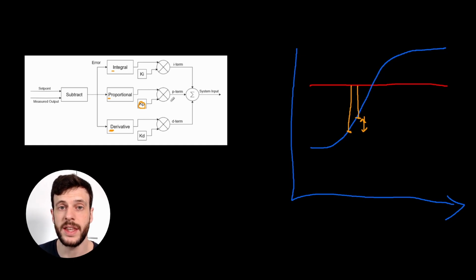And by doing that, we can get an initial system input from the P term, which is quite close, an additional I term, which helps correct for steady state errors, and a D term, which stops us from correcting too much. And this provides what we call damping. It means the controller doesn't respond too fast to a change. And we'll see where this is useful with the visualization tool. So let's take a look at the visualization tool.